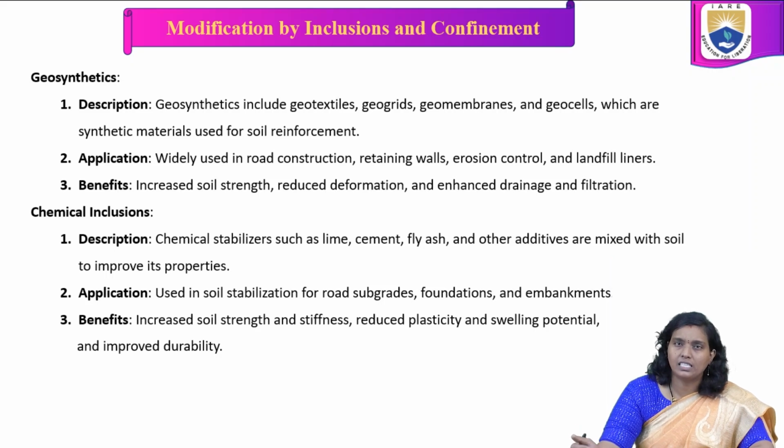Geosynthetics: these include geotextiles, geogrids, geomembranes and geocells, which are synthetic materials used for soil reinforcement. We choose geosynthetics as a modification by inclusion for getting better soil conditions or desired soil properties.